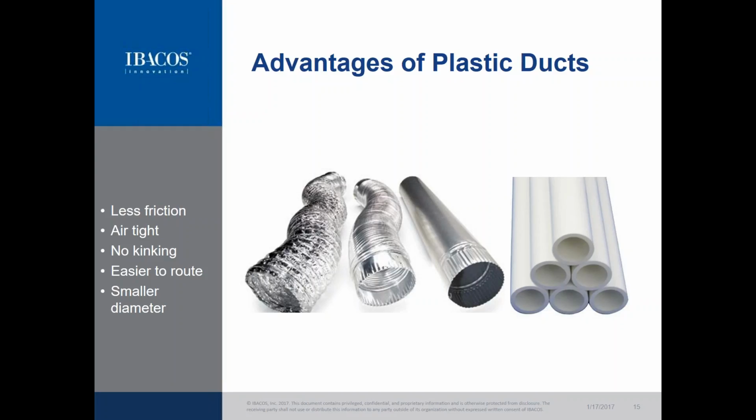Flex ducts, there are small diameter flex ducts, but they incorporate some problems in regard to installation flexibility and also kinking and also just the friction rate within the duct itself. So that's where we're looking at plastic ducts that have smooth interior surface walls that provide less friction, that are ultimately airtight. We've tested plastic ducts that are not even welded or sealed, and they're very airtight.